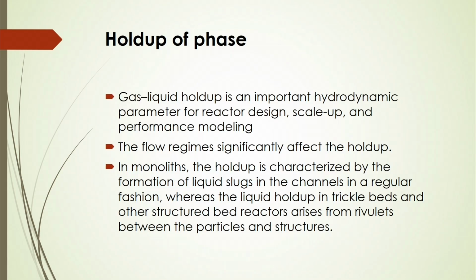Next, one of the important hydrodynamic factors is called hold up of the phases. What is that hold up of the phases? Now, if you are considering two phases like gas and liquid, then it is the volume of the individual phase that is occupied in that particular channel of the reactor.